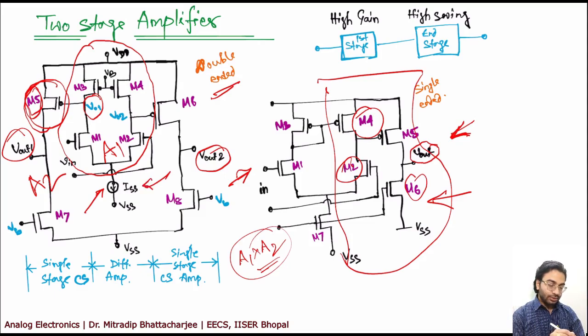Okay, so if you see this circuit, you have a current source, right? Now when you replace this current source with a current mirror, you can get n number of current sources associated with different circuits, right? Because in a chip you cannot put a source inside. Generally the chips are very small.